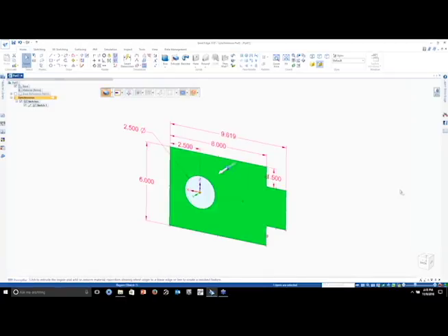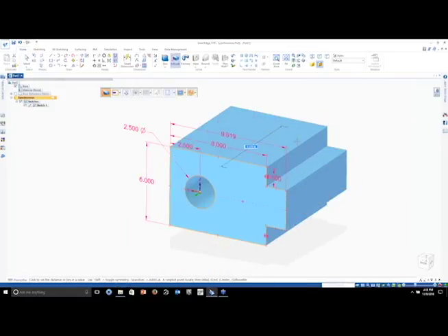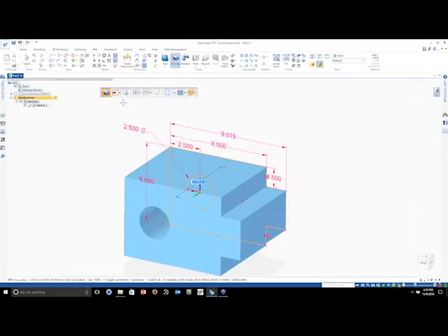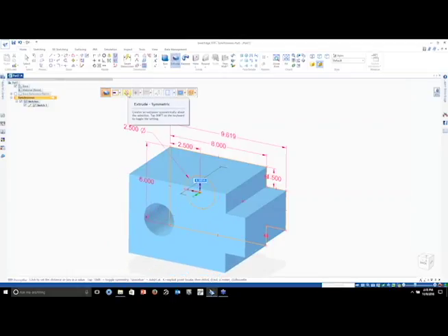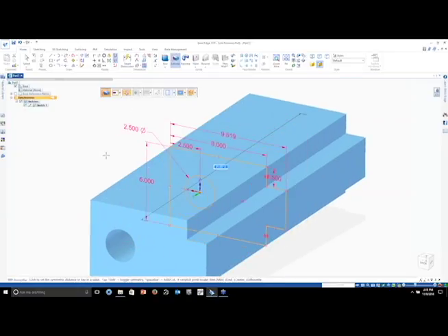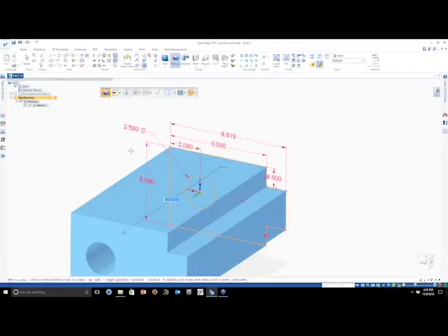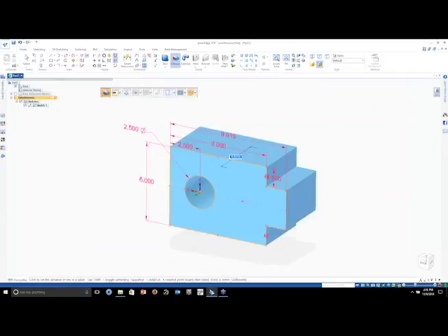And what we want to do with your sketches and regions is create geometry from them. So at this point, with the closed region, which we have right here, I can go ahead and grab that. So I'm just using my select tool, select my region. Again, there's that arrow I was talking about. When I grab that arrow, it immediately starts turning into a protrusion. So it's going to ask you which direction you want to go, one way or the next.